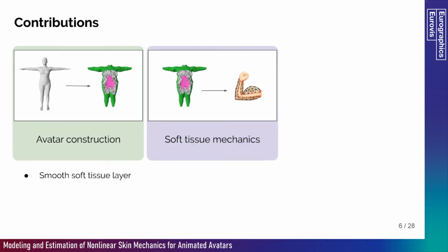This soft tissue layer is simulated using an elastic FEM, while we propose a novel elastic deformation metric and a custom anisotropic nonlinear material. Thanks to the alternative deformation metric, we preserve all the surface details of the data-driven model when the avatar is in static poses. With the custom material, we improve capture fittings and external interaction capabilities.